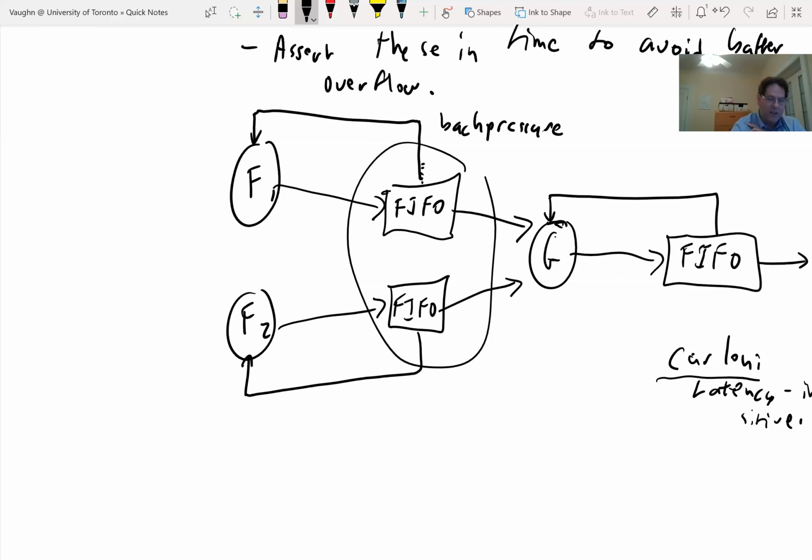For a system like this, which is feed forward, you won't get deadlock as long as your FIFOs are big enough. You have to be careful if you made very small FIFOs. And if you have loops in your design, you have to think carefully about whether you could ever get a situation where you're waiting for somebody to compute a value, but they will never get that value because some FIFO is full, and you'll never pull anything out of that FIFO until the downstream module can compute.